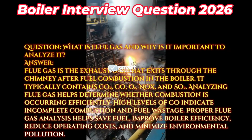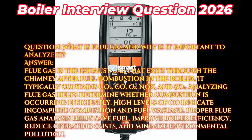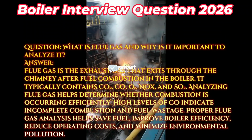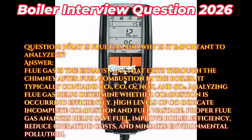Question: What is flue gas and why is it important to analyze it? Answer: Flue gas is the exhaust gas that exits through the chimney after fuel combustion in the boiler. It typically contains CO2, CO, O2, NOx, and SO2. Analyzing flue gas helps determine whether combustion is occurring efficiently. High levels of CO indicate incomplete combustion and fuel wastage. Proper flue gas analysis helps save fuel, improve boiler efficiency, reduce operating costs, and minimize environmental pollution.